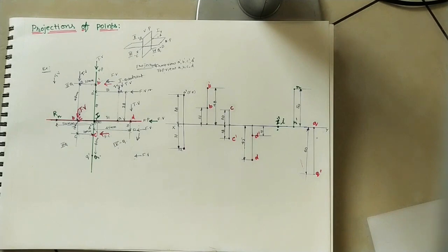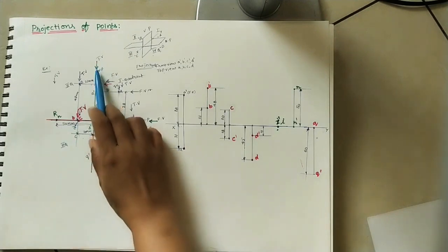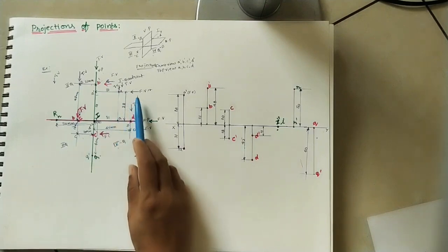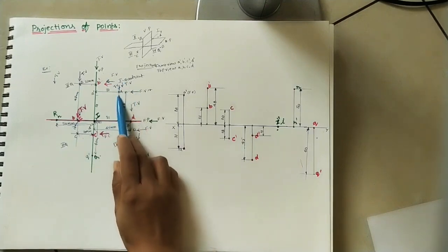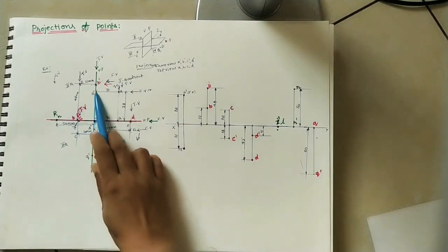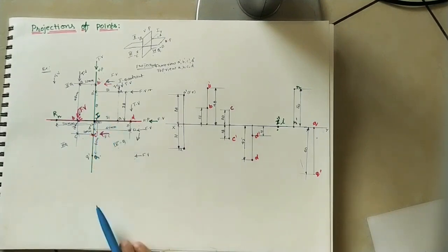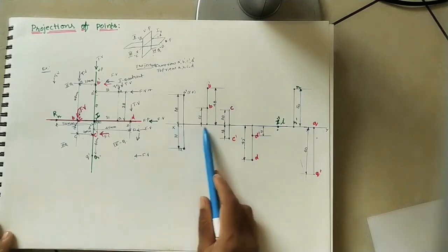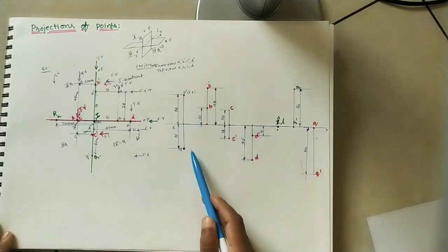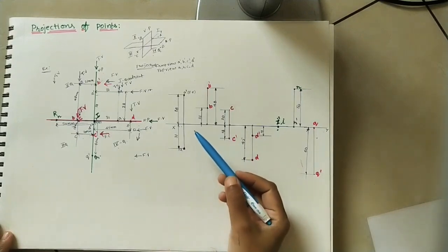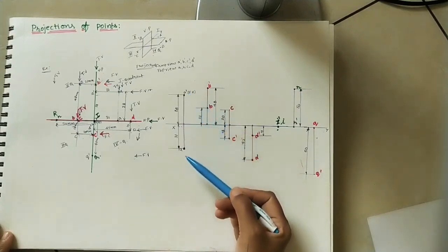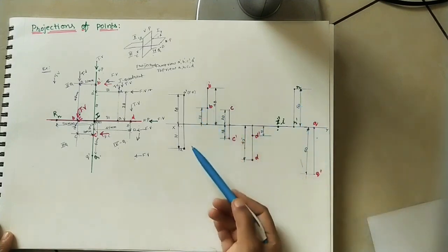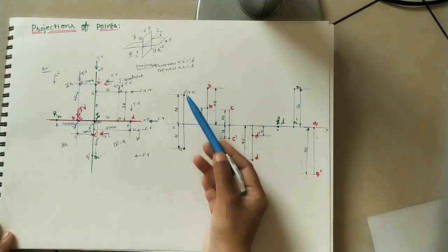In this type of question, initially you have to roughly draw the horizontal plane and vertical plane, and mark the given point. Okay, after that you have to assume the front view and top view of that point and roughly mark the projections of those points. And in the working sheet, in the drawing sheet, you have to draw the XY line and mark the projections. Here make sure you take both front view and top view on the same line. Okay, in all the cases, because we are taking one single point, both projections are coming on the same line.